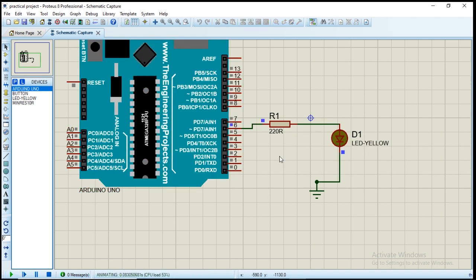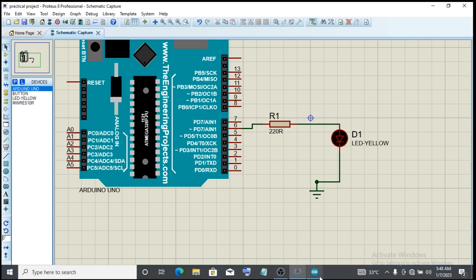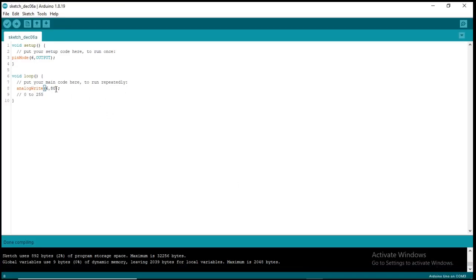If you look at this LED, you see that it's getting darker because of the value that I changed. So whenever I want full brightness, what I need to do is increase the value of that analogWrite. You see. So let me increase it one more time, then we'll stop this video because it's getting long. Let me go to our Arduino IDE and make it 255, which is the maximum value you can go to.